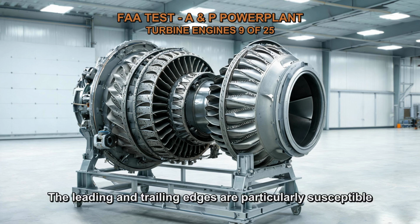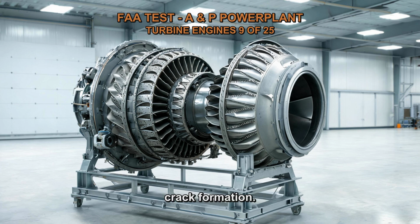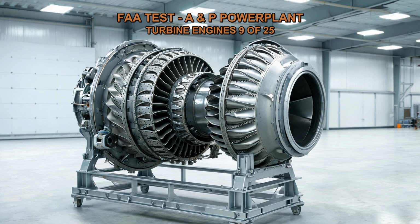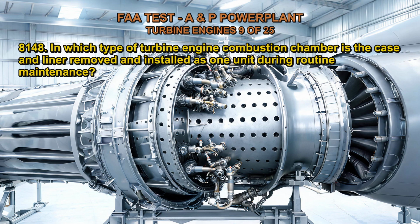The leading and trailing edges are particularly susceptible to stress concentrations, making them common locations for crack formation. The high-temperature operating conditions, combined with cyclic loading and thermal gradients, contribute to the development of stress rupture cracks. The stresses can arise from factors such as centrifugal forces, aerodynamic forces, and thermal expansion mismatches.